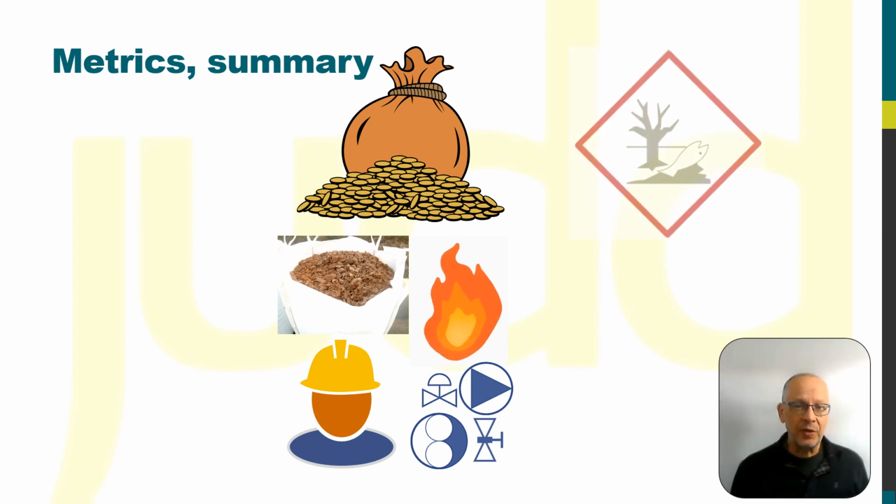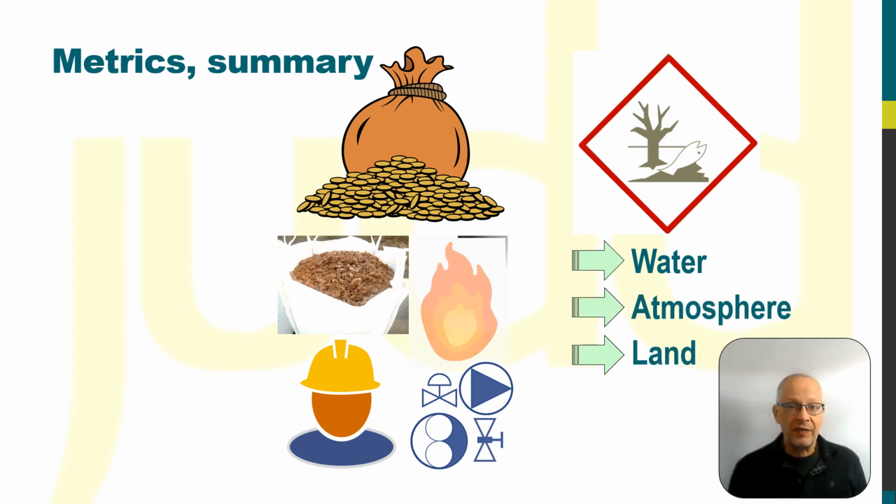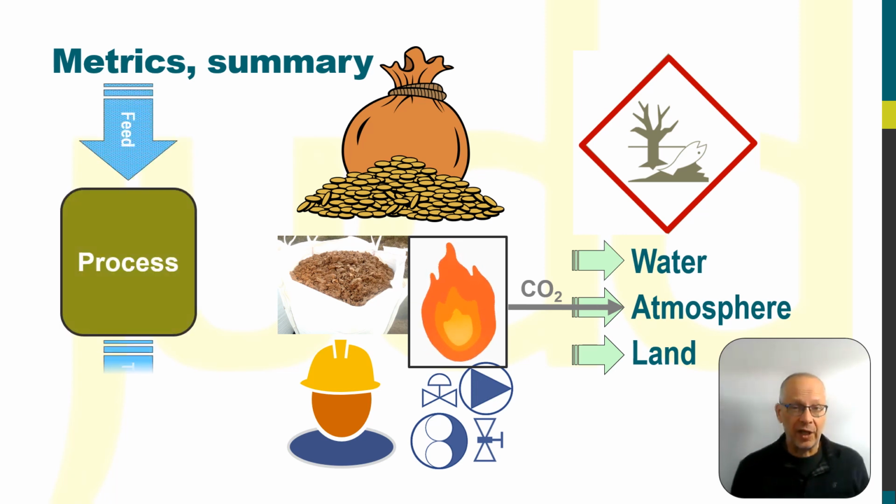Environmental impact assessment should take account of impacts of discharges to water, land, and to the atmosphere, with the impact of energy consumption quantifiable as the equivalent discharge of CO2. These metrics complement the more commonly used one of purification performance.